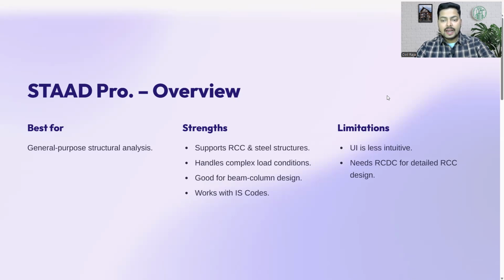Now, the second limitation, which is the biggest limitation of this software as per me, is that it needs RCDC for detailed RCC design. That means if you are going to design a building in STAAD Pro, then obviously it will do the analysis and design. But for the detailing, you will have to jump to RCDC. So if you are combining these two softwares, STAAD Pro and RCDC, it is very good software. Like you can easily design any building in this one.